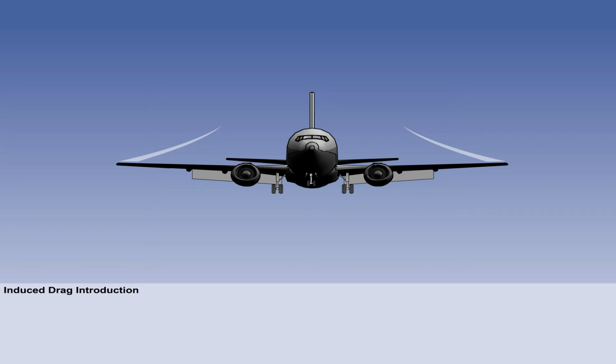Induced drag is an undesirable byproduct of lift. Wingtip vortices modify upwash and downwash in the vicinity of the wing, and these changes in the relative airflow produce a rearward component in the lift vector, known as induced drag or lift-dependent drag. At low indicated airspeeds, IASs, the angle of attack will be greater than at high speed, and this will produce stronger vortices. The stronger the vortices are, the greater will be the induced drag.